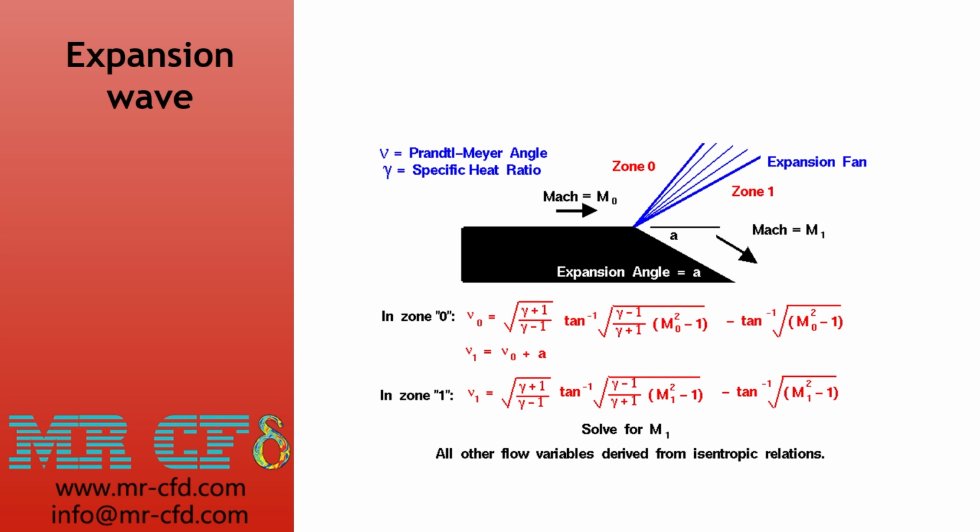So as we said in the beginning, the supersonic expansion fan is technically known as a Prandtl-Meyer expansion fan. A two-dimensional simple wave, it is a centered expansion fan process that occurs when the supersonic flow turns around a convex corner. The fan consists of an infinite number of Mach waves diverging from a sharp corner. When the flow turns around a smooth and circular corner, these waves can be extended backward to meet at a point. Each wave in the expansion fan turns the flow gradually in small steps, since it is physically impossible for the flow to turn through a single shock wave, because this would violate the second law of thermodynamics.